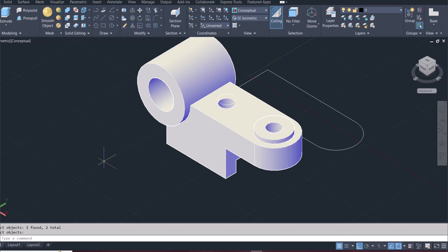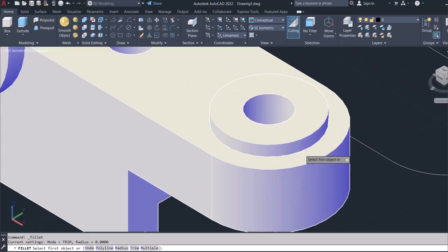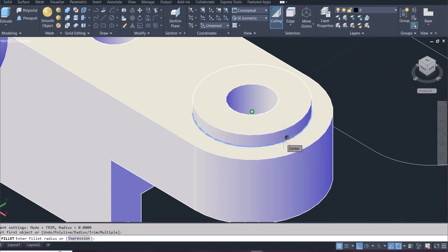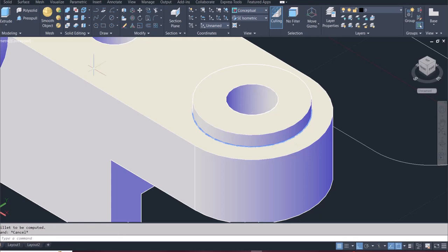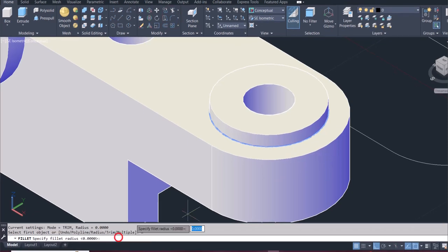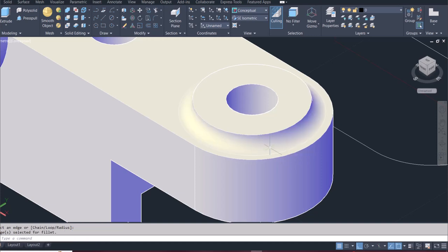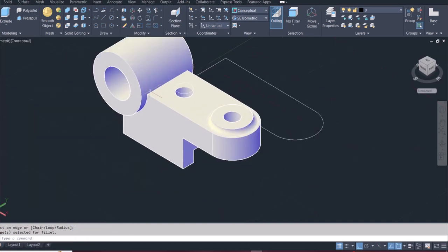I think what I should do next is provide a fillet. So there's a fillet around here, and that fillet radius there should be R3. So all fillets and rounds R3. So let me go back for fillet, and then the radius 3. So I'll select this curve, then hit enter, then enter again. So that is my R3.